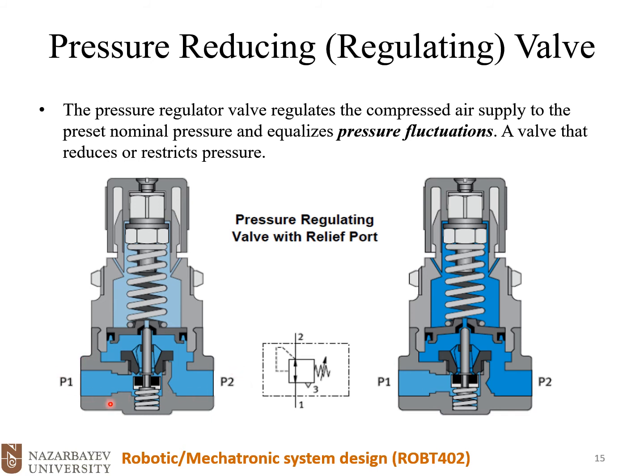The air comes from port P1 into this chamber here, and we have a spring and a set screw with which we can change the compression of the spring.